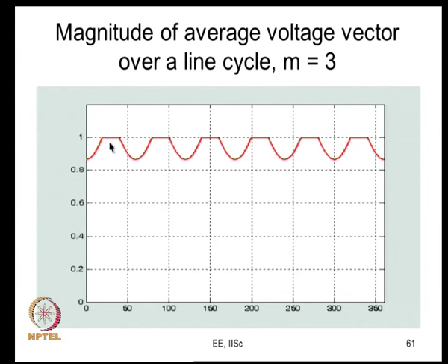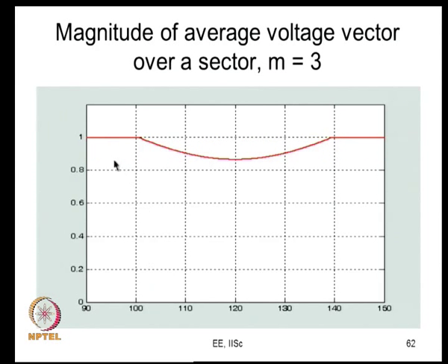So if you look at the magnitudes, they are 1. What do you mean by magnitude being 1? An active vector is actually being applied. Here it is another active vector is being applied. So if you look at just one sector, up to this its active vector 1 is being applied, and then here active vector 2 is applied, and what is happening in between? There is switching between active vector 1 and active vector 2. So in all these subcycles you switch for active vector 1 and 2 only, null vector is never applied.